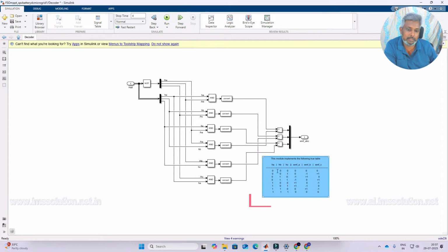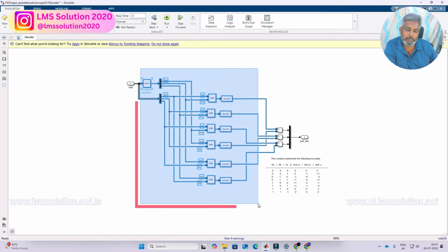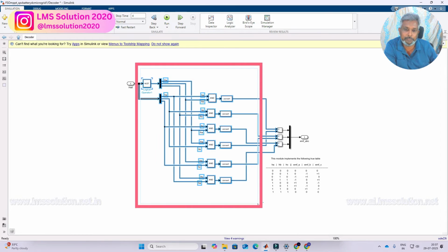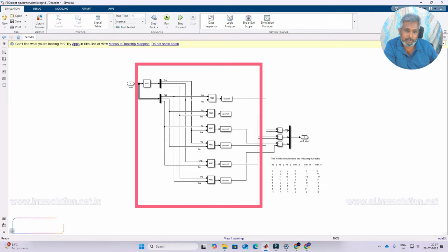For each Hall sensor output, it has a digital output of 0 and 1. For each Hall sensor output, we need to map it to the back EMF calculation. So this is the calculation for back EMF. This is the implementation diagram of that conversion of Hall sensor into back EMF. We are just using AND operations. Here is the drive for calculating back EMF of EA, EB, EC.